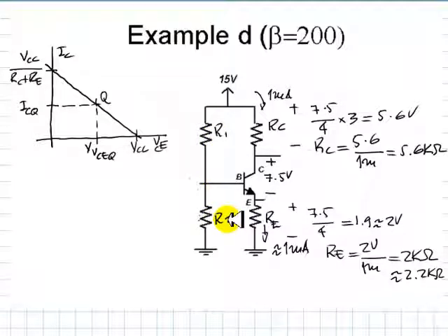Apart from ensuring that the transistor is in its active mode, this configuration, the voltage divider common emitter one, is so popular because it has one very important feature. You see, transistors, as we've said in the lecture, don't have a predictable beta. I mean, when we purchase them, we don't really know what beta we're going to get for a given transistor. Once we have them, that beta can even change with temperature. We want to design the bias circuit so that the Q is whatever we want it to be, regardless of the beta. How do we ensure that?